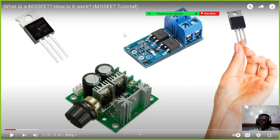And sometimes persons are working with circuits like this, and they are not certain if they are MOSFET. Right, so especially persons who are not knowledgeable about transistors, they will look at these and think that they are regulators, because regulators look like this as well, and persons might believe that they are BJT. But most of the time for these type of switching circuits, they use MOSFETs, especially for this type of power switching circuits.